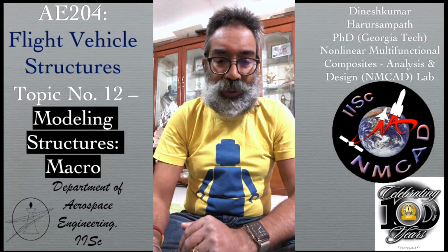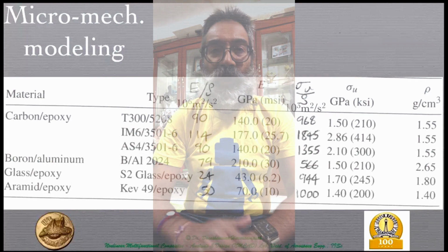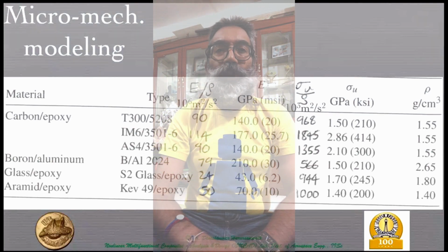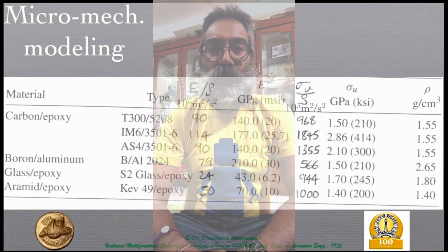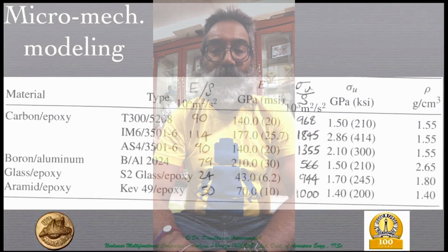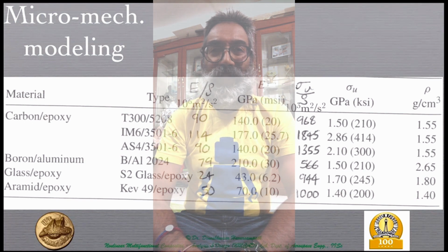So I'll just put up a table from your textbook along with a few additional columns associated with the two of the material performance indices that we introduced. Of course, we introduced the stiffness in a form that is suitable for dynamics as square root of E by rho.